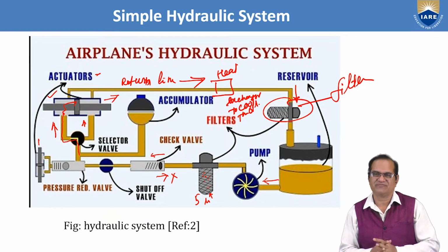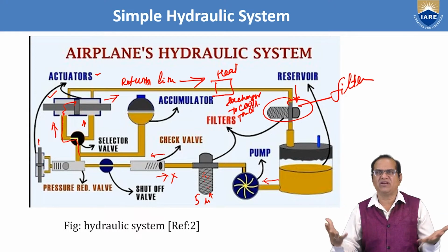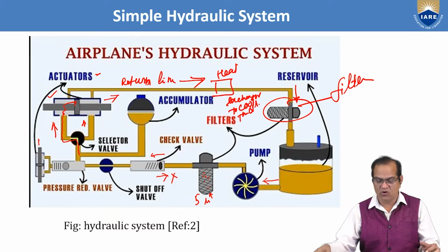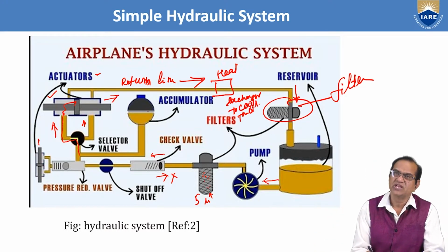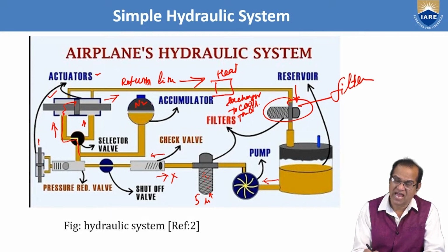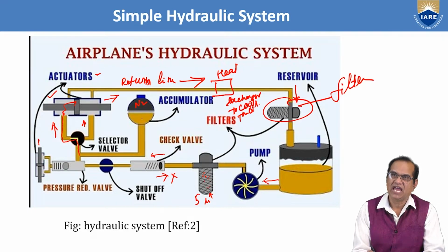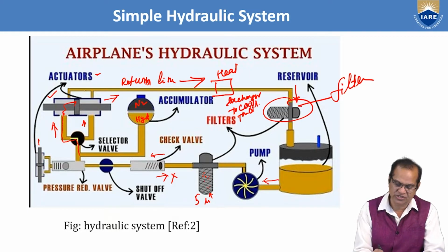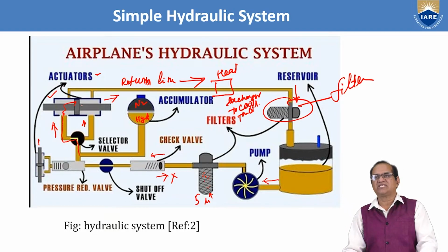It is not like this. You have so many valves, pressures, accumulators. Okay, so accumulators are here. This accumulator here is charged by nitrogen. High pressure nitrogen is charged. And here, if you see, we have the hydraulic fluid. This hydraulic fluid is pressurized and your system is working in this fashion.